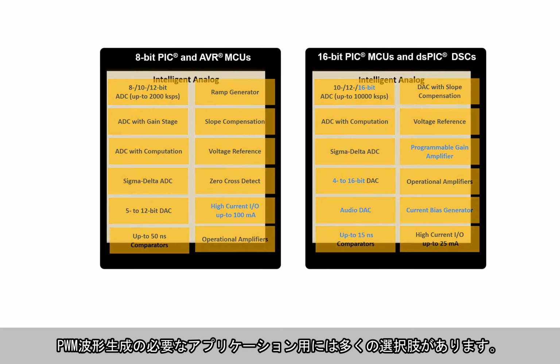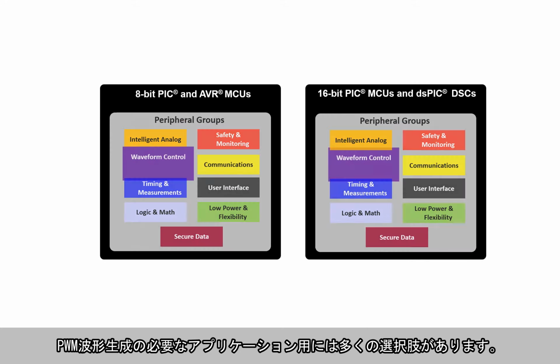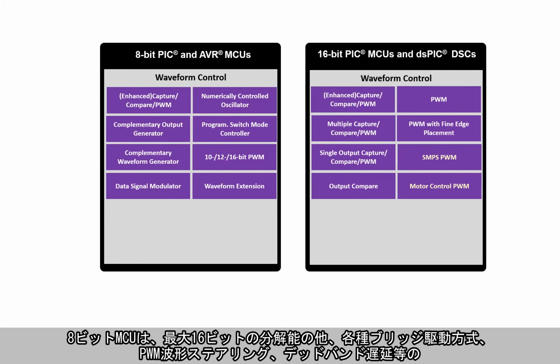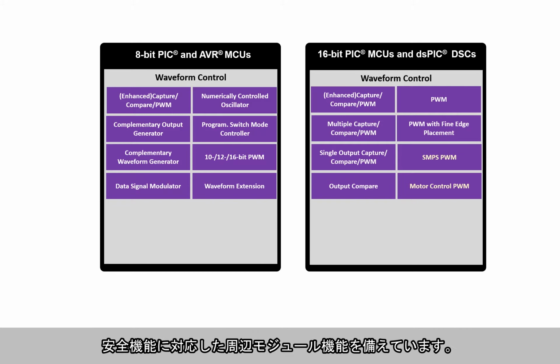Designers requiring PWM waveform generation in their application have many options to choose from. 8-bit microcontrollers provide options for up to 16 bits resolution, with additional peripheral capabilities that accommodate various bridge drive topologies, PWM waveform steering, and safety features like integrated deadband delay.